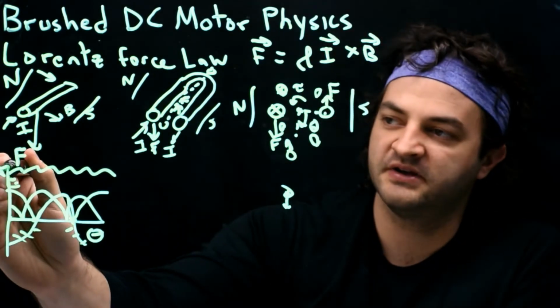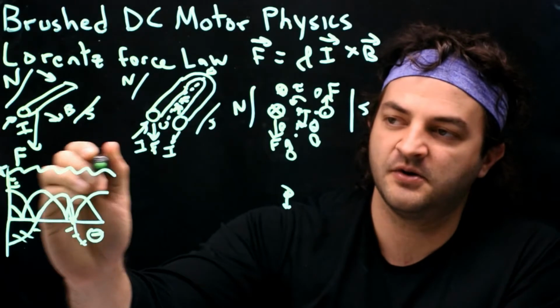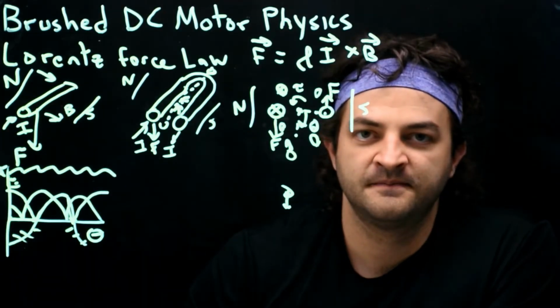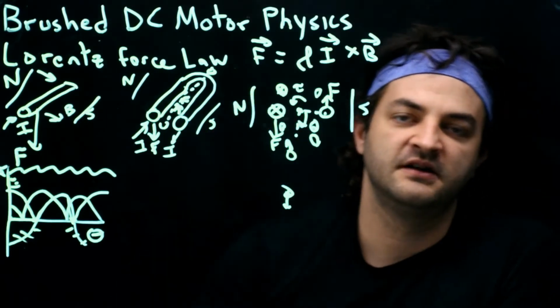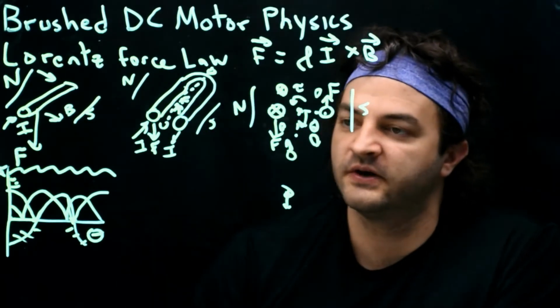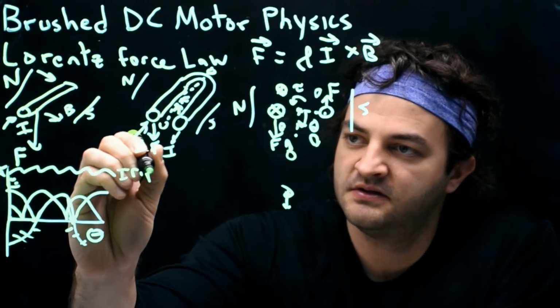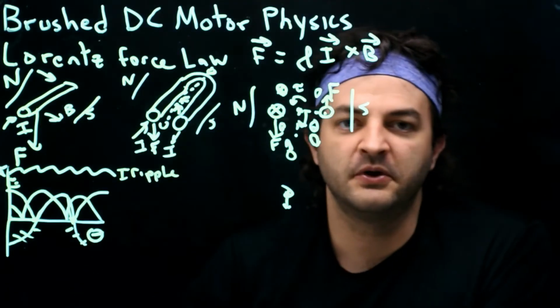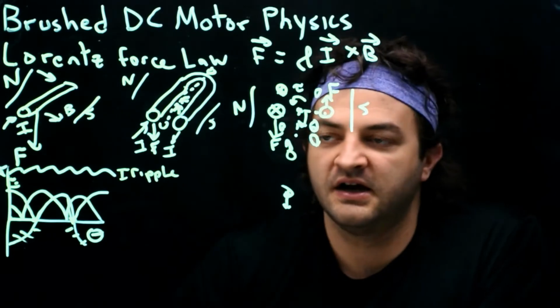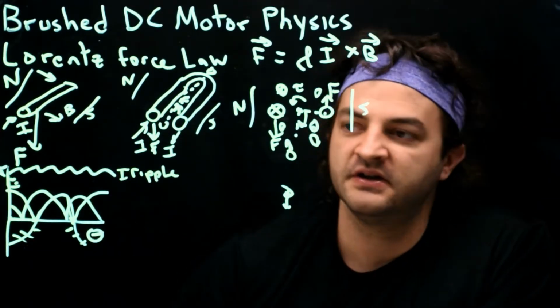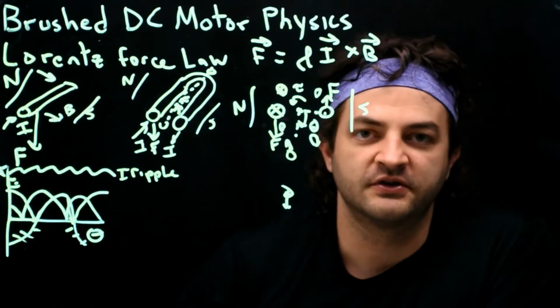And you could see what we have is almost a constant amount of torque versus angle, based on the ability of putting current into the coils. And this isn't constant, really. There's some ripple. So every motor that we build is going to not have constant torque with angle, but we'll approximate it as constant torque with angle. And the amount of torque will be proportional to the current.